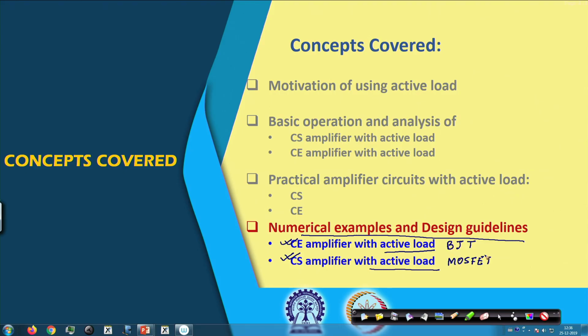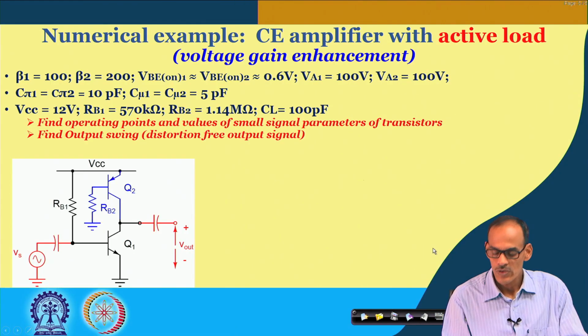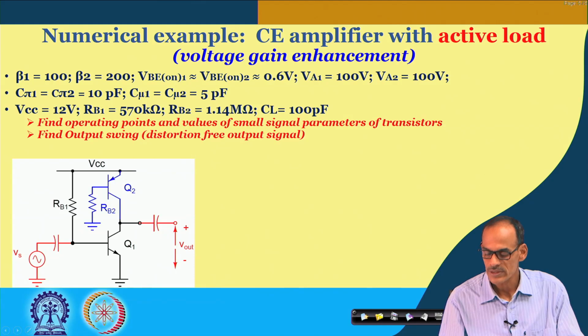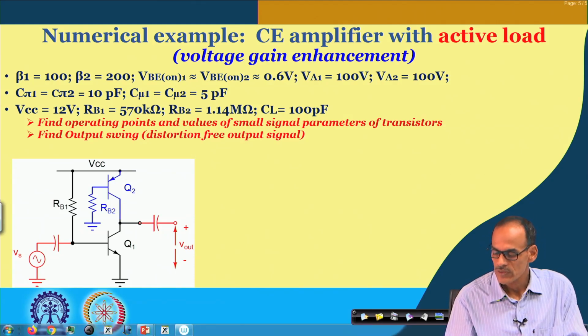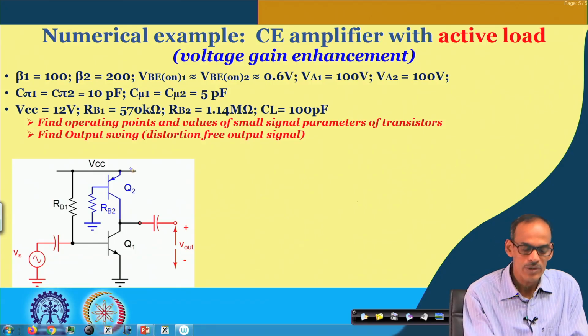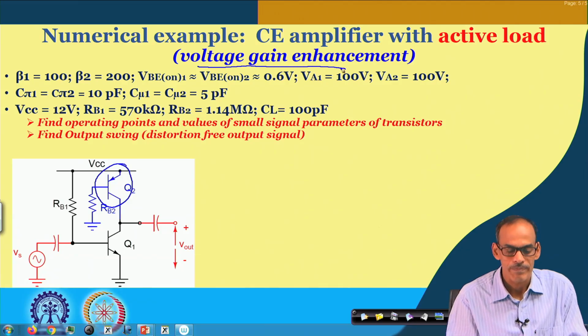So, let me directly come to the circuit. Here we do have an example. In the previous discussion we already mentioned that instead of having a passive load, we like to use active load, and the purpose, as we discussed, is to enhance the voltage gain.